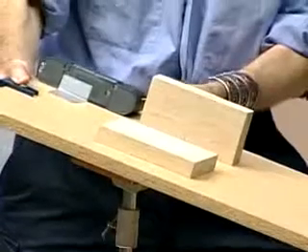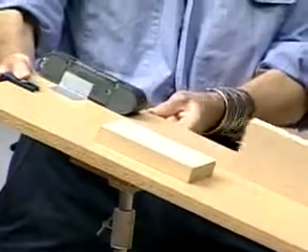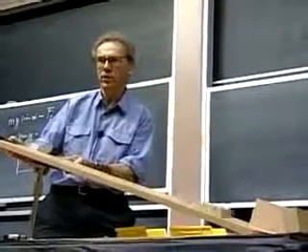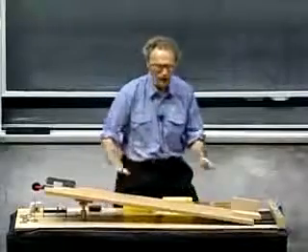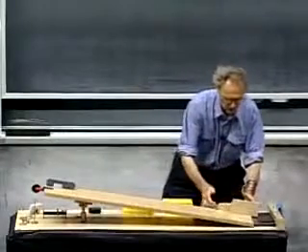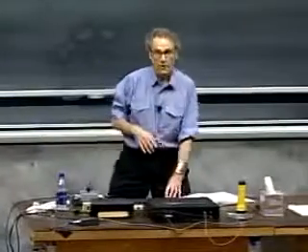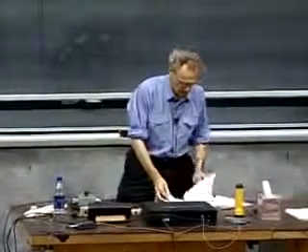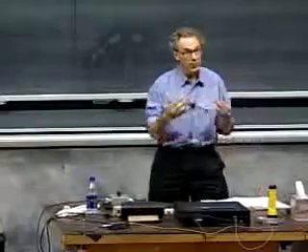14 degrees, 16, 18. One goes and the other one follows within 0.2 of a degree. And the reason why there's always some difference, of course, is that the plank is not exactly uniform. I have to be careful that I don't touch the critical surfaces. So you have seen a difference in friction coefficients, and you have seen there's almost no effect of surface area, and there's no effect of the mass. And that is both very non-intuitive.